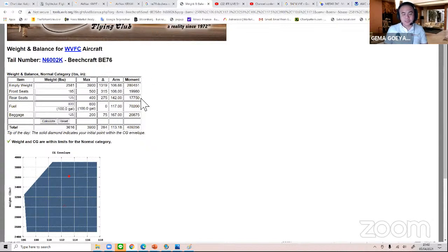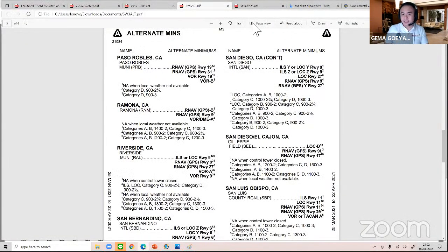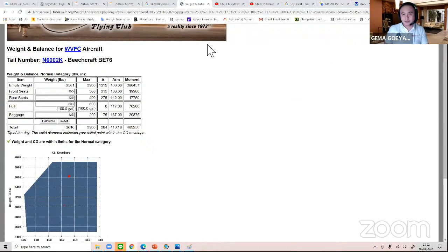But in the Duchess, you have to check your airplane's single engine positive rate of climb based on the weight. It's about 3,400 something. So if you want to maintain single engine climb, the single engine gradient is 1.5% on Part 23 twin engine.